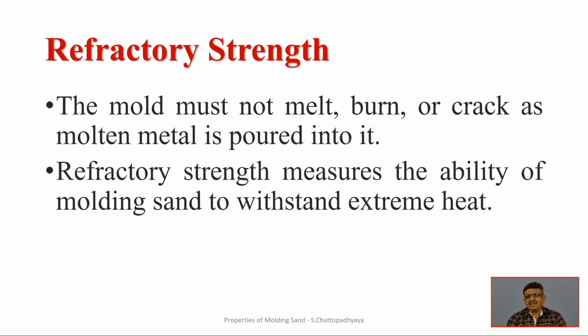And refractory strength, refractory properties are also very relevant, because we are choosing moulding sand. The reason is that it will retain its shape and its composition will not be jeopardized at elevated temperature. Sometimes we have to keep the temperature 100 degrees above the melting point, and that can be, for steel and other things, 1635 or above that.